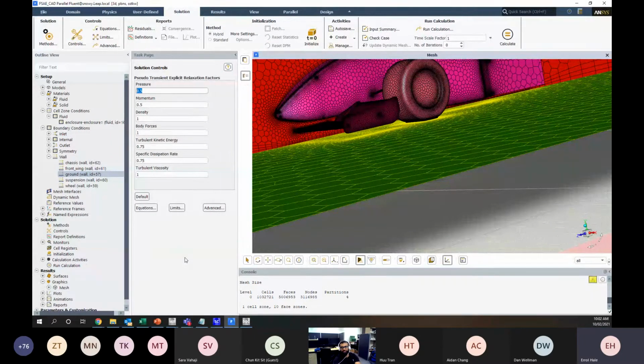so we're solving an iterative solution. At iteration 1, there's a value for pressure. At iteration 2, we've calculated a second value for pressure. An under relaxation factor will take half of that difference rather than take iteration 2's value. And that will basically allow us to converge more stably to a solution.